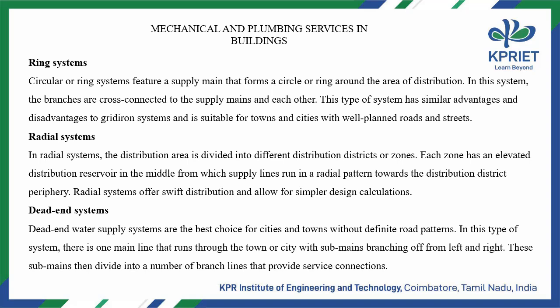In radial systems, the distribution area is divided into different distribution districts or zones. Each zone has an elevated distribution reservoir in the middle from which supply lines run in a radial pattern towards the distribution district periphery. Radial systems offer swift distribution and allow for simpler design calculations.